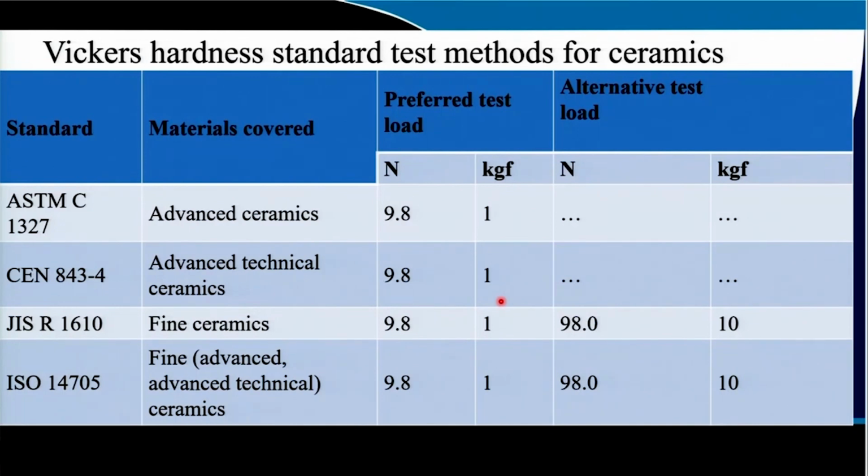On the other hand, for very low hardness materials like copper and magnesium, the load varies from around 25 to 50 gram force. The other parameters remain almost the same, and you find the Vickers hardness number, which gives perfectly reliable results with no fluctuations. The error is quite minimum in Vickers hardness testing.